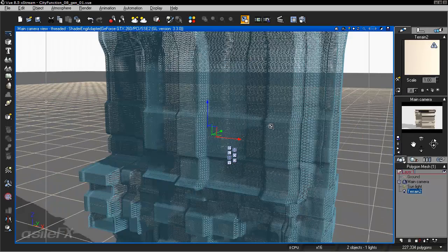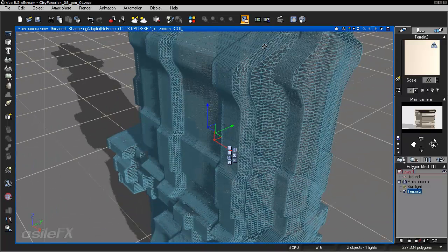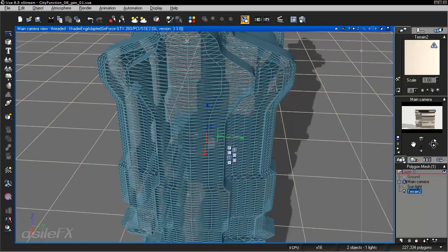we can see because of the way this was extruded as a terrain, we really don't have a lot of geometry around the sides. And the way I rotated the object and flipped it up differently than its original output gave me more control in creating these displacements because most of the geometry was along this direction. Displacing it on the sides could be problematic because there really is not a lot of geometry there.